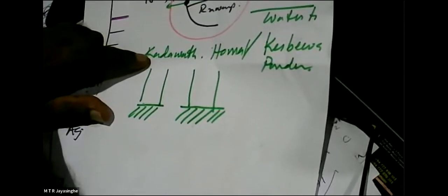The moment you have basements and bury the structure in the soil, there are two advantages. What are the advantages? The structure is firmly fixed on the soil. The second advantage is, because we are removing soil, you can add the same weight and the soil will find nothing has happened. So the stress in the soil will be zero. For about 20 floors, you will find the weight of the soil removed from the basement is equal to the weight of the building you have constructed. So soil will not know that the building has been constructed. And then the settlements will be minimal.